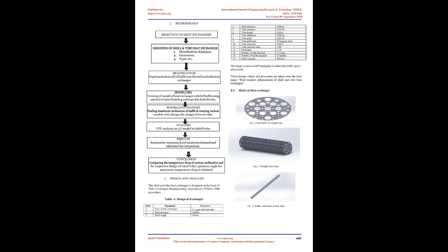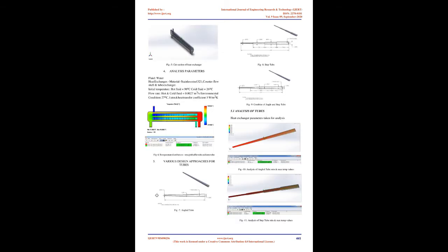A set of tubes is called the tube bundle and can be made up of several types of tubes: plain, longitudinally finned, etc. Shell and tube heat exchangers are typically used for high pressure applications, with pressures greater than 30 bar and temperatures greater than 260 degrees Celsius. This is because shell and tube heat exchangers are robust due to their shape. Several thermal design features must be considered when designing the tubes in the shell and tube heat exchangers.